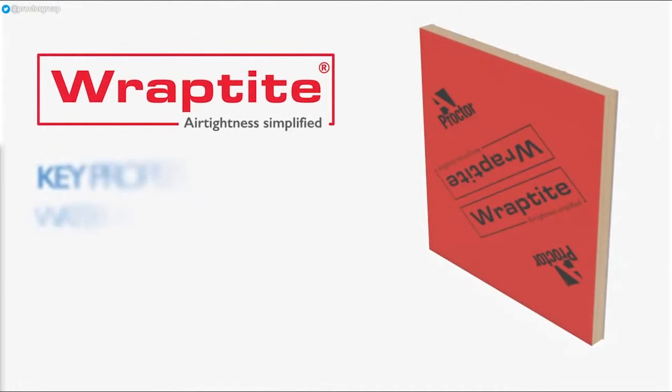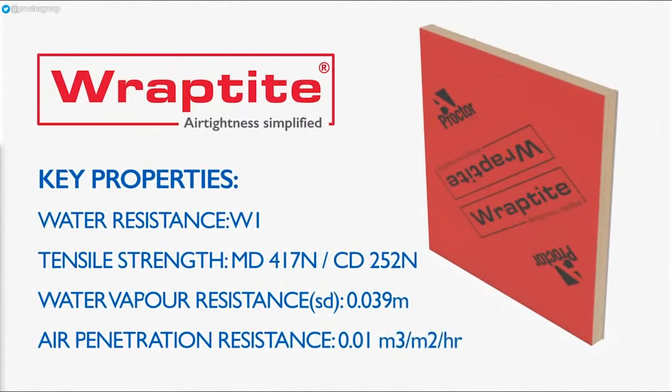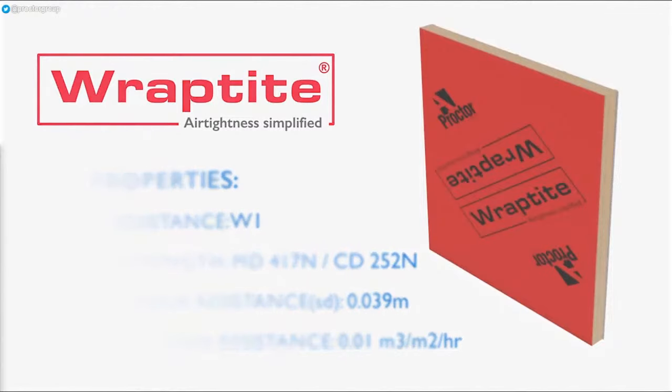The wrap-tight air barrier membrane is designed to adhere to the external face of the timber frame panels to provide an effective and robust barrier to the movement of air. By moving the airtight layer externally, wrap-tight greatly simplifies the installation of building services internally, as less account must be taken of penetrations. The mechanical durability of wrap-tight, further enhanced by being fully bonded to the substrate, ensures the air barrier layer can be factory installed and transported to site whilst maintaining its integrity. Being highly weather resistant with a W1 rating, the membrane provides effective temporary weather protection as well as ensuring the building meets its designed air leakage rate targets, reducing the likelihood of expensive and time-consuming remediation.